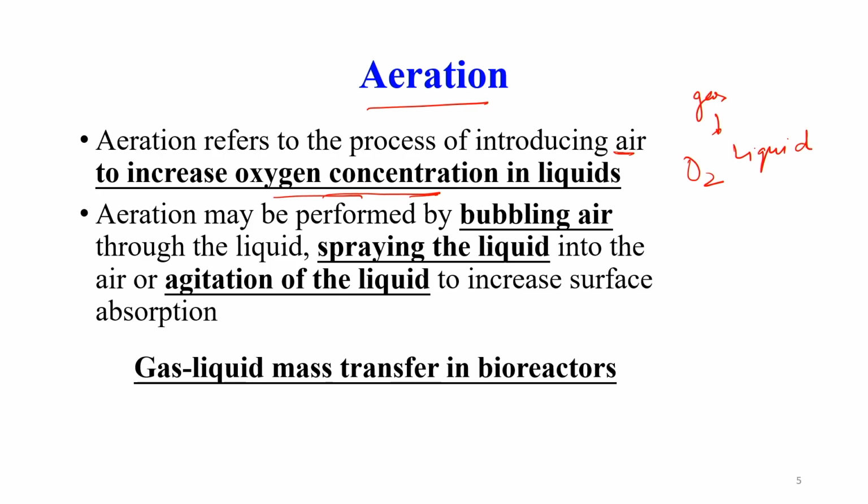Now, it can be done by bubbling air through the liquid, by spraying the liquid into air, or agitating the liquid to increase the surface absorption. Mostly we will be focusing on aerating with bubbles, that comes under aeration, and agitating the liquid comes under mixing.